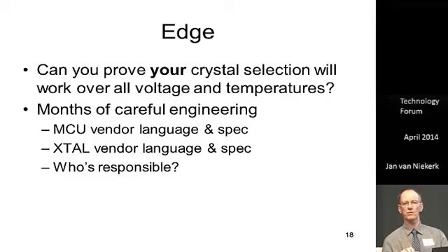And that is the crystal that you're putting on your microcontroller is a trap for the unwary. Because you go, okay, microcontroller and a crystal, I stick them together and they oscillate. But how do you know that they will oscillate forever? And how do you know that they will oscillate at minus 20 degrees centigrade? And how do you know that they will oscillate when the next batch of microcontrollers come from your vendor, where the guy tweaked the needle with the boron deposit slightly, and the gain of the little amplifier in there that runs the oscillator is 10% lower.